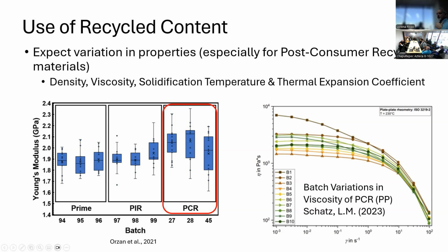If you mix in recycled content here, the variations that you're going to see are going to be very small compared to virgin materials. However, for consumer products, post-consumer waste is a lot more complicated, because now we're dealing with how you separate a plastic bag from a housing of some sort, and how you keep those streams clean.